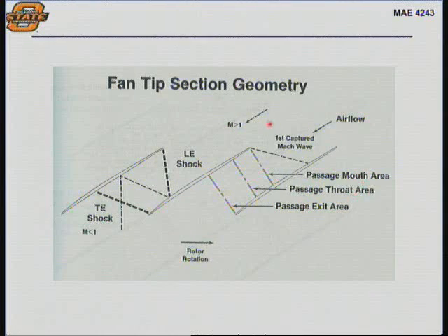Near the tip, where you have the very high Mach numbers, you are now designing this passage to minimize the amount of shock losses. You're going to have shocks. They're going to impinge on boundary layers. And your goal is to minimize this, like you were minimizing the shocks in a supersonic inlet. So a lot of care goes into this passage design. And by the way, just as a side note, when we have supersonic flow at the tips of fans and they produce these shock waves rotating really fast, that produces a very